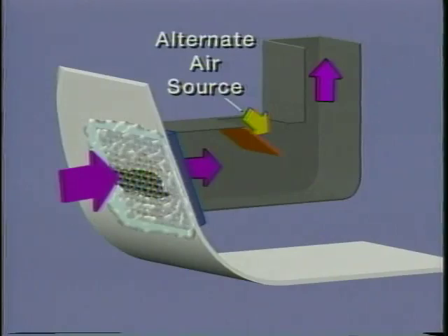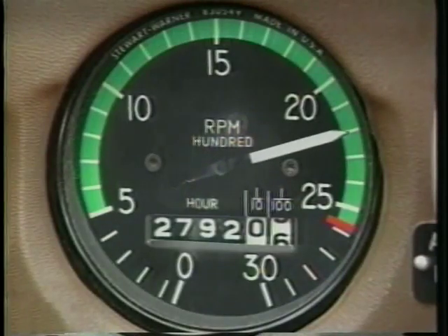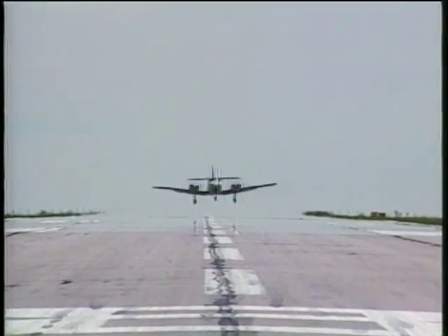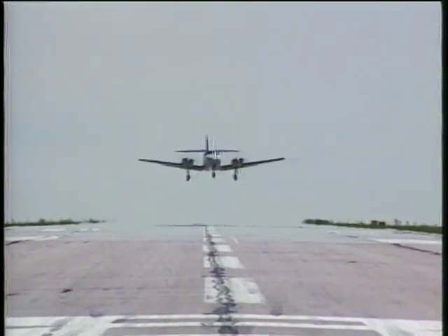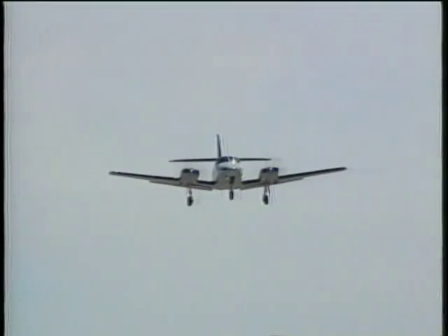Although this allows the engine to keep running, the reduced airflow and increased temperature affects the amount of power the engine can produce, much like the effect carburetor heat has on a carbureted engine. Although it may sound like fuel injection is the perfect system, it does have some drawbacks, the most significant being the increased possibility of vapor lock.